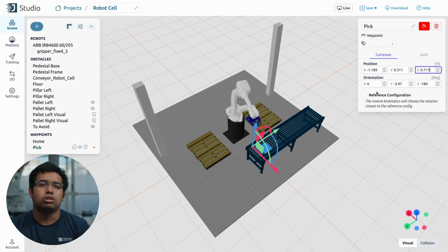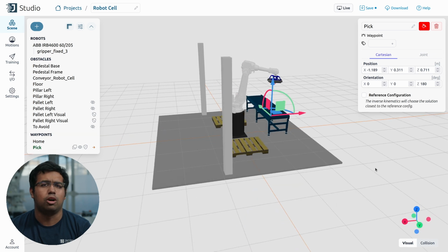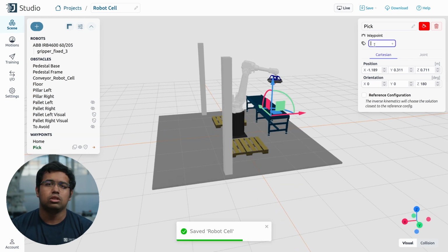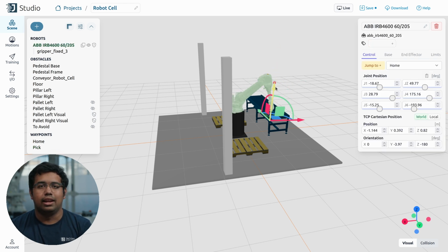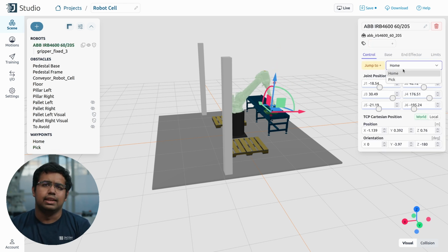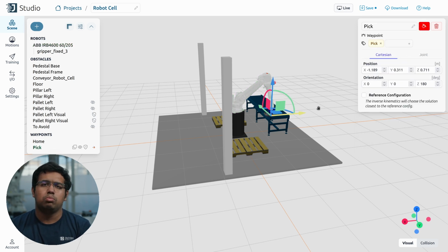The pick point needs to be on the corner of the conveyor or whatever delivery system you have for your boxes for palletizing, a constant corner that can be used as a reference regardless of box size. For example, all of our boxes are aligned and end up at this corner, so we'd set this as our pick point. Here, I'd use a Cartesian coordinate, because we care more about getting to this point than we do about exact joint values. After all, we could get any different size of box showing up here, and we don't want to make joint values fixed, or it can't adapt to that.